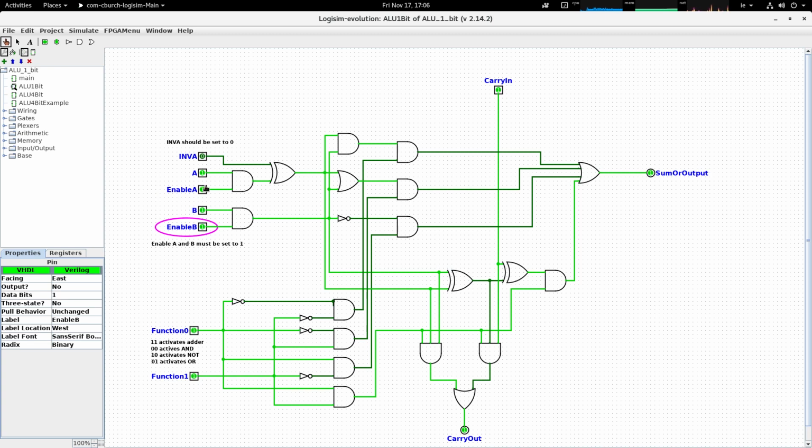Now the inputs A and B and the carry in are equal to 1, so that's the same thing as adding 1 plus 1 plus 1, which, as you'll recall from your binary addition facts, is equal to a sum output of 1 and a carry out of 1. So that seems to be entirely in order, and while the circuit is active, we can look at the individual components and make a little bit of an observation.